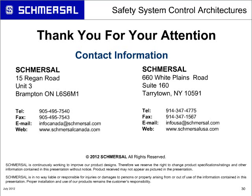And you can get safety switches that monitor just the actuator that are locking switches. You can also get safety locking switches that monitor the lock and the actuator. And that's a big difference. If you get a safety switch that only monitors the actuator and doesn't monitor the lock, you're not using that for residual motion type of applications. That's more process control. You just don't want somebody opening up the door in the middle of a process.